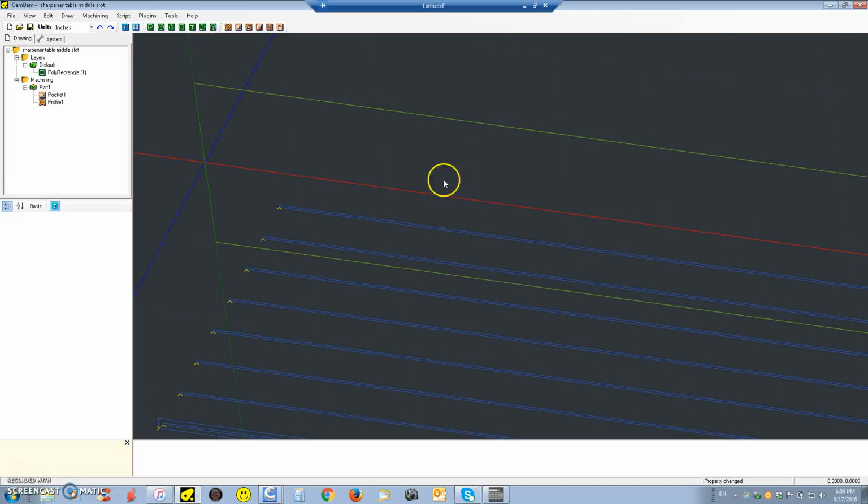Well, I learned that if you try to cut a slot that's fairly deep compared to the width of the bit, and you actually expect that the slot is going to be exactly the size of the bit, there will be no room for clearing the material. You're always better to use a smaller bit, and somehow move up and down and have some clearing room.